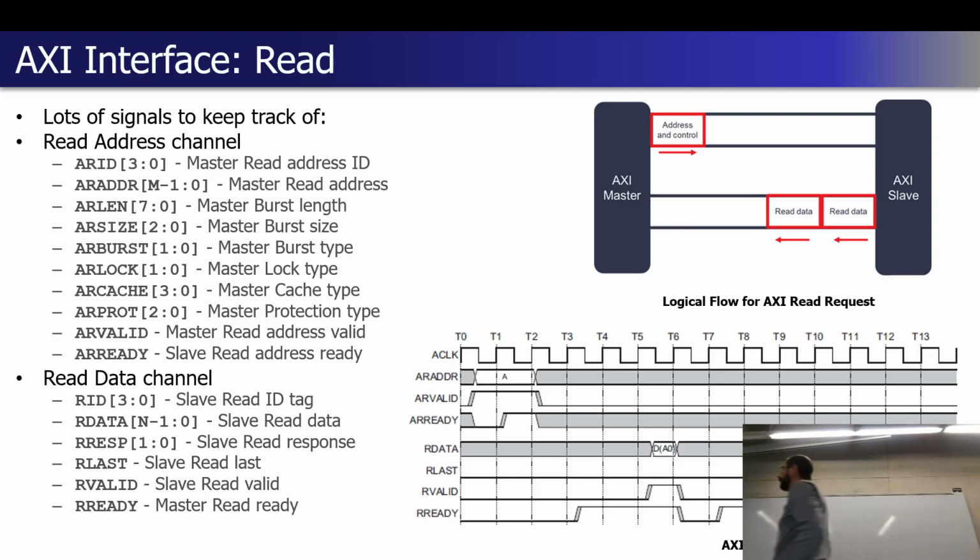Yeah, sure. So on here, you've got AR length for the burst length. What's the difference between that and burst size? Yeah, and then there's also AR burst for burst type. Burst type, I have to look at the documentation. There's different bursts where, for reasons that aren't immediately obvious unless you're working with DMA type systems and interfacing to FIFOs, sometimes you want to burst and you want to send to the same address multiple times.